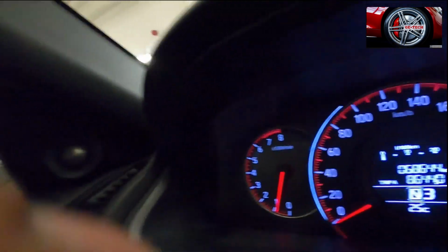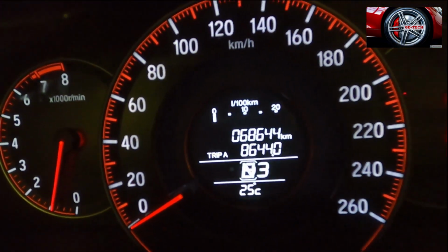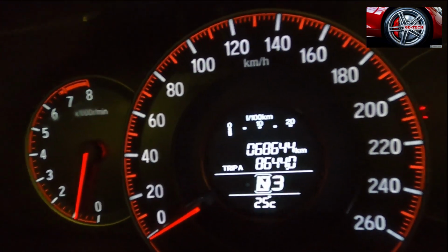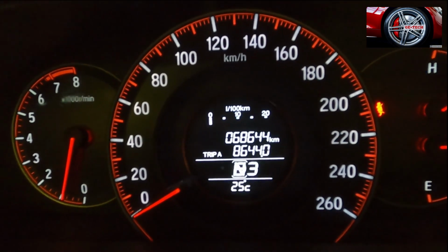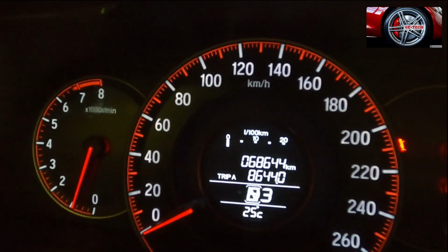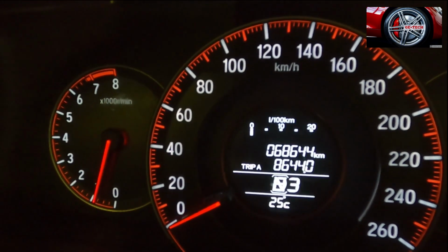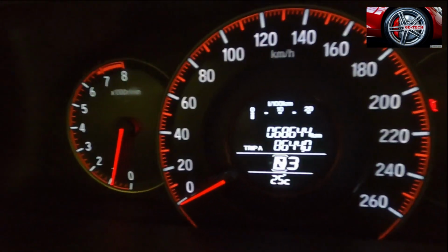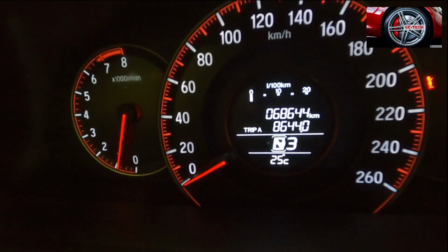So what I notice here is he has a malfunction indicator light. There is a malfunction indicator light blinking on his gauge control panel, and it was MIL for transmission. So that is D3, neutral and D3.